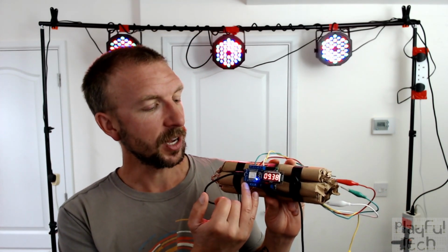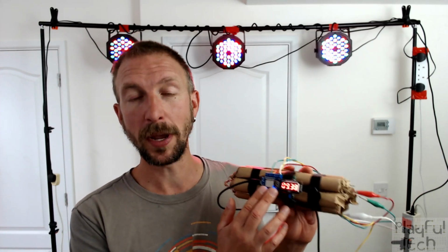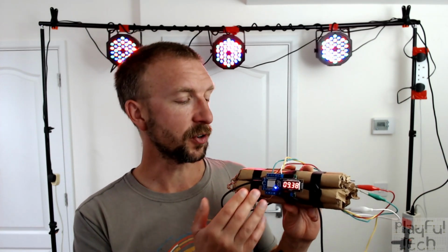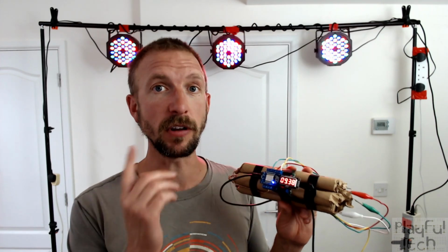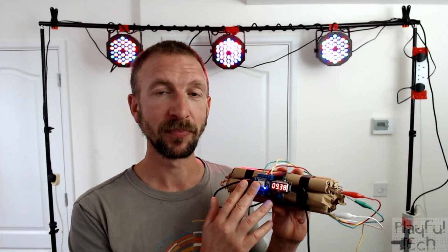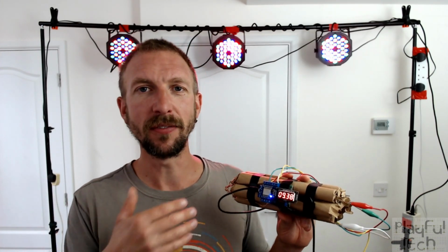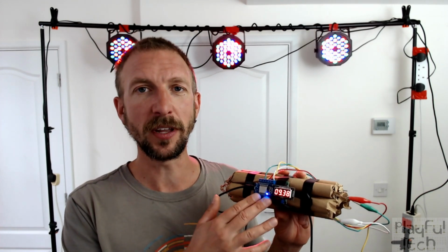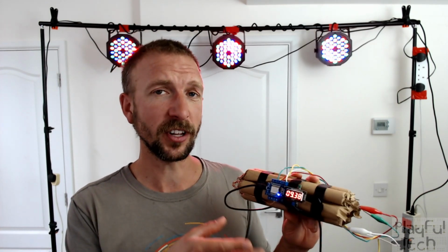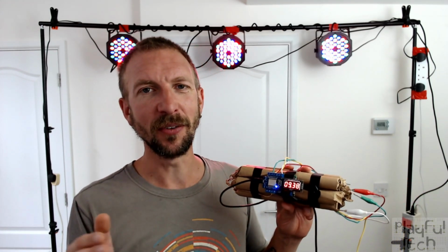They have fewer overall pins than an Arduino. They've got 8 digital pins and only 1 analog input pin. On a Nano you'd have 13 digital pins and 8 analog pins, so it's substantially less. Also some of those pins themselves have slightly weird behaviours.